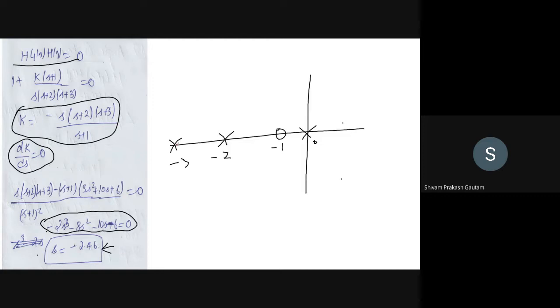So here was our root locus branch where we need a breakaway point. The breakaway point, you can see, minus 2.46, is satisfying this criteria. The other 2 locations which you will get from this cubic equation will not satisfy the criteria. So let us suppose approximately we have minus 2.46 at this point. At this point, our root locus branch will leave the real axis.